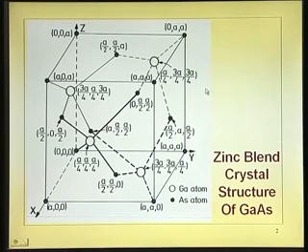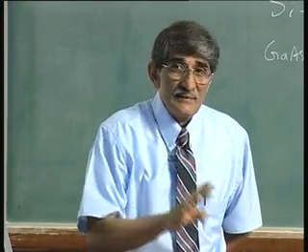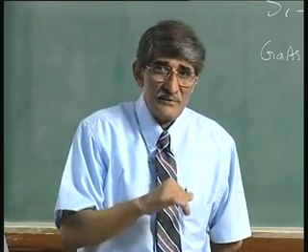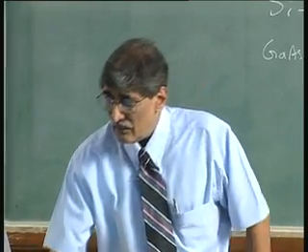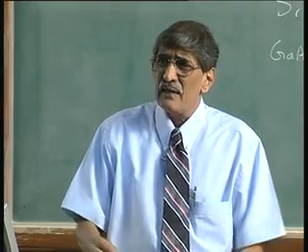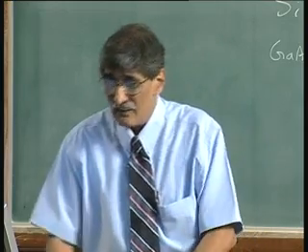Here you can see these are the lines which I have drawn, because gallium has got 5 valence electrons. This is the difference between silicon and gallium arsenide. Silicon has got 4 valence electrons. Okay. Now, on an average therefore, for gallium and arsenic there are 8, like in silicon. So, this structure also is forming covalent bonds. This also forms covalent bonds like silicon, but in addition to that there may be slight ionicity because of slight negative charge, that we will discuss later. Right now we will see.